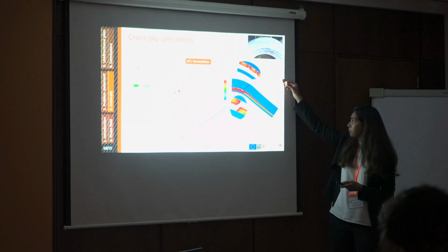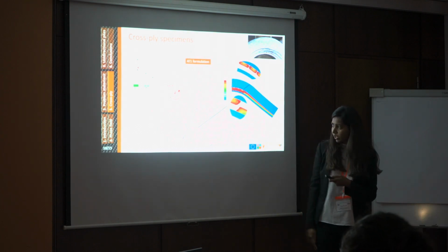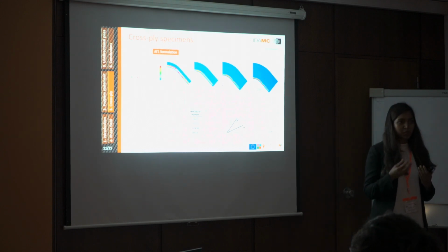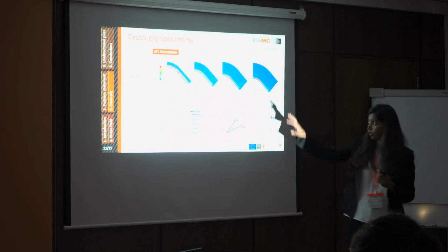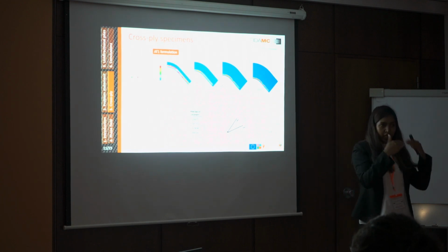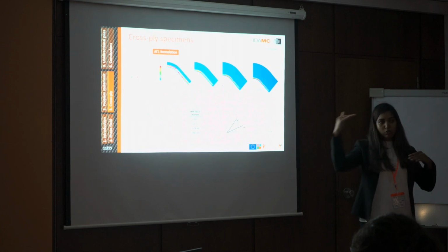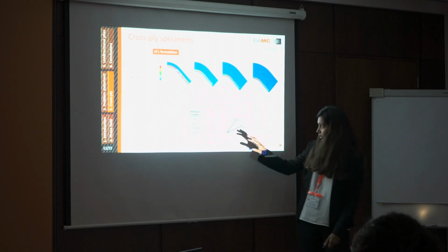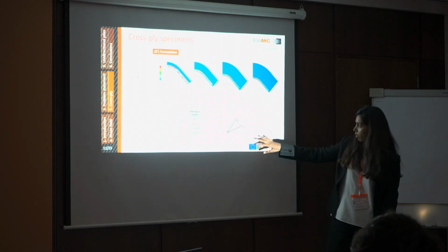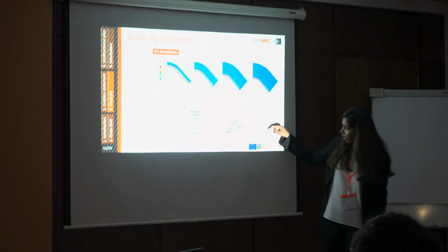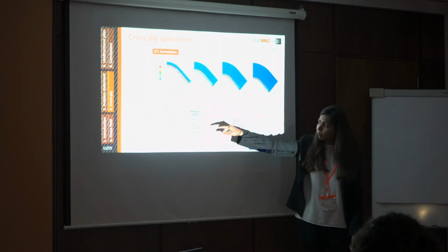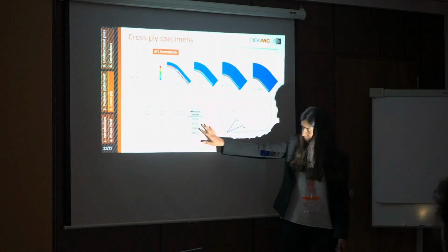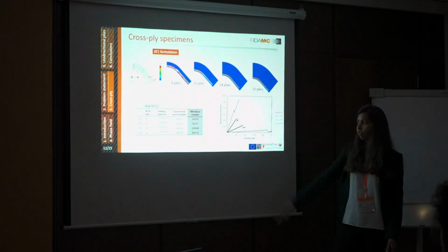So this is the moment versus rotation graph, and we checked the formulation for specimens with 8, 16, 24 and 32 plies, and we obtained the same behavior: debonding happens in the 90-degree ply in the bottom, travels to the top of the 90-degree ply, leaving behind a transverse crack and then multiple transverse cracks. We took the peak moment values for all the samples and compared them with the experiments. Here we have perfect correlation between the experimental failure moment and the numerical failure moment.